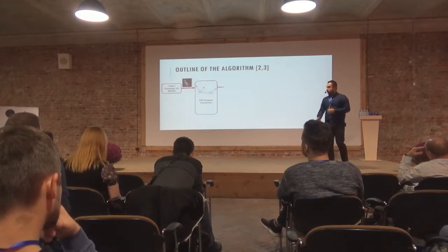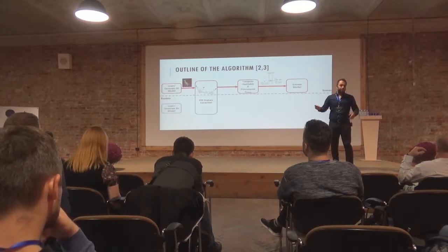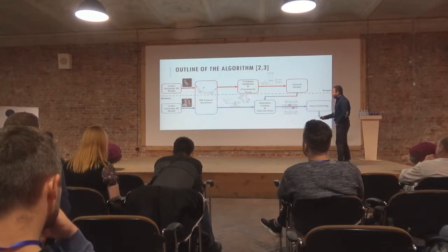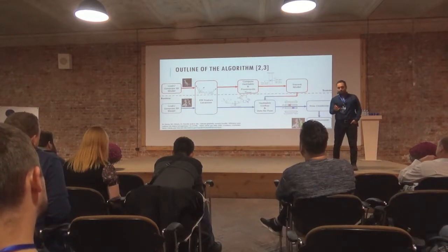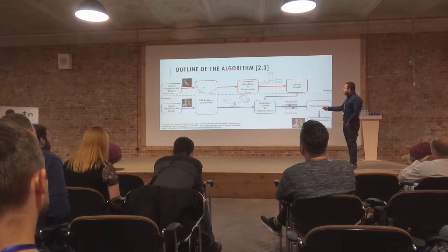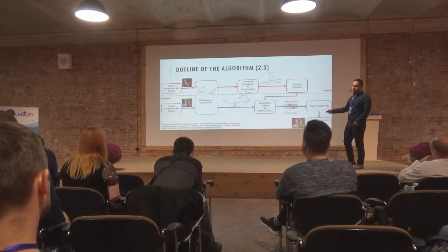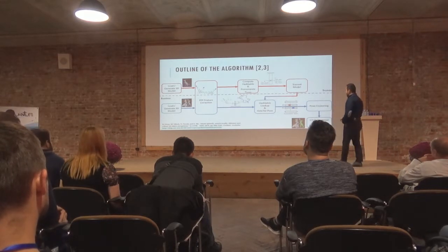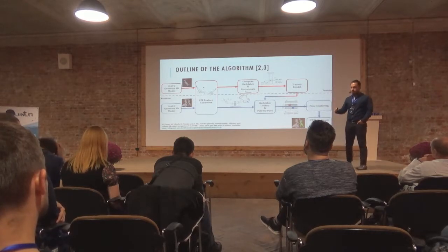So the idea is the following: we have a CAD model, and let's do some feature extraction on it. This can be done in many ways, but there can be certain choices. We put this CAD model into a database, really just a database, nothing more, with all these extracted features. It's an inverted file, which gives you, for each feature, which points on the model can generate it. It's basically hashing. And this you call the trained model. This is just a geometric training of the CAD model.